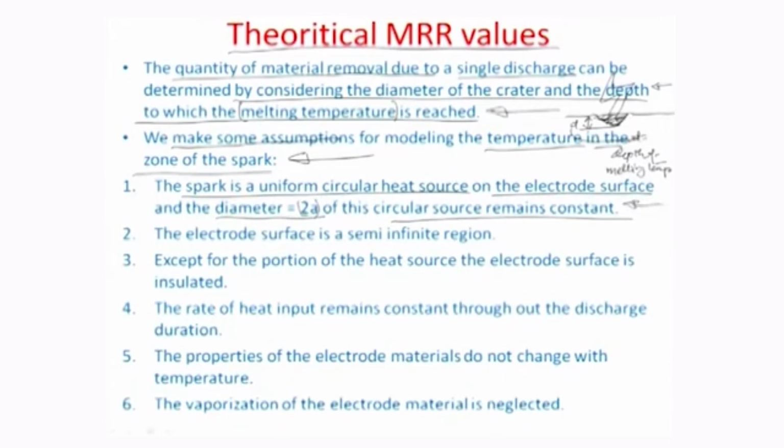So therefore, we do not vary the diameter in our model, assuming that the approximate tentative diameter of striking on the surface is the same, even though the spark may have some characteristics of variability, but at least the heat transfer is taking place across a circular area if we consider the spark to be like a cylinder of constant size.